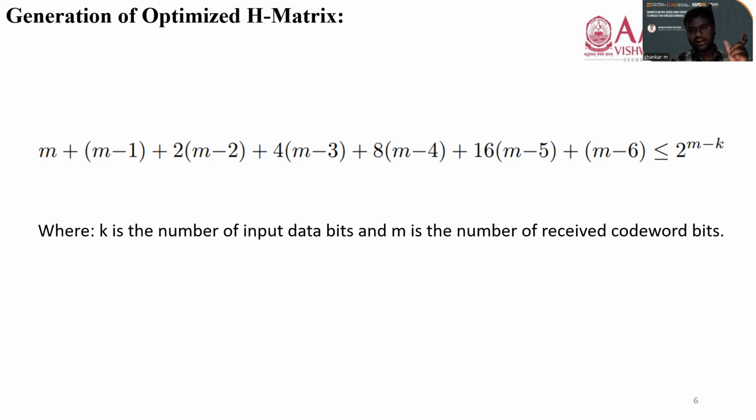Once you write all the possible error sequences, we are going to compute something called parity bits. Parity bits are the bits which will be tagged with the input data in the memory, and will be used for detection and correction of the input data. If there is any error in the input data, by using these parity bits we can find where the error is and how to correct that error.